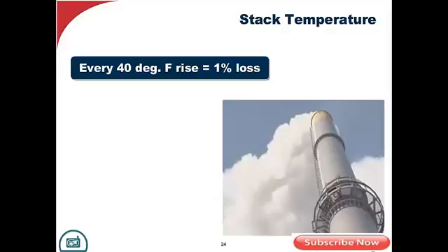And what causes that? Sooting on the fire side, scaling on the water side. I'm impeding the heat transfer across those tubes, whether it be a water tube or a fire tube. So the first thing is to make sure you've got a very reliable stack thermometer in that stack, and you very conscientiously log temperatures against pressure, firing rate, ambient temperature, and feed water temperature. Very, very important. Because when you see something like this occur, something's gone on with that boiler. And 9 chances out of 10, it's the water side of that boiler or the fire side that's either gotten fouled from soot or scale.